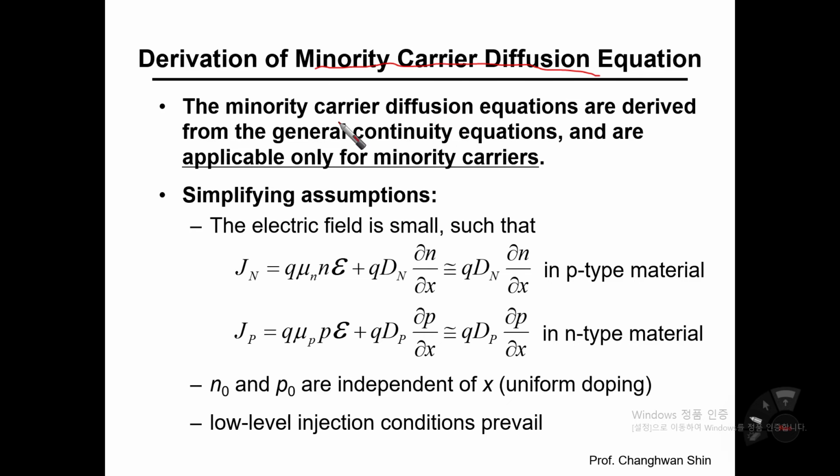For your information, we have p-type material and n-type material. Those are two different silicon materials that are contacted physically together, and now the n side is grounded and the p side is biased. Suppose you apply a positive voltage onto the p side. As you know, p-type material has a bunch of holes, and n-type material has a bunch of electrons.